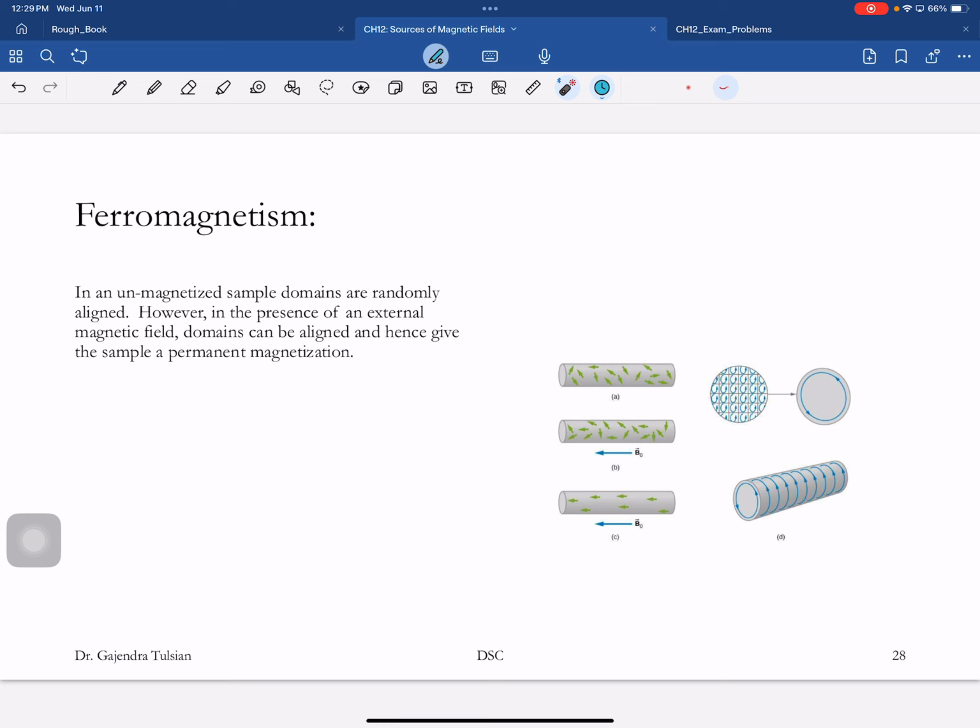So there are soft magnetic materials, which you apply this current and they'll line up, and when you remove the current, they'll go back to the random shape, so they'll lose their magnetism. And that's useful because you can pass a current like this, have them line up, then pass a current in the opposite direction, have them line up in the opposite direction. And so you can change the orientation of the magnet as needed.